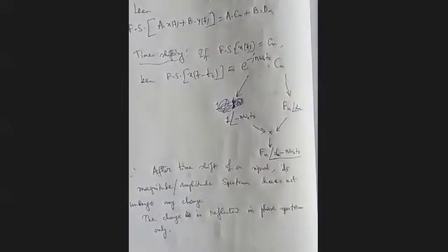So if we plot phase spectrum versus n, there is a change, but in the magnitude spectrum, it does not have any change. So that's why from the phase property only, we can have the idea whether a signal is shifted in time or not.